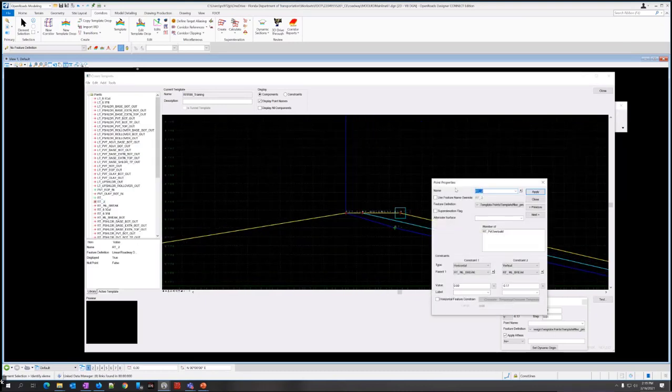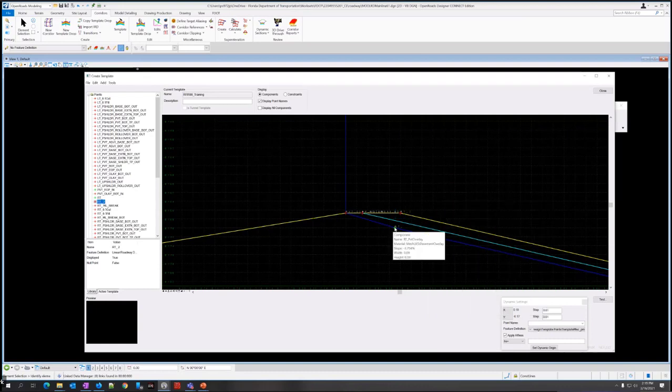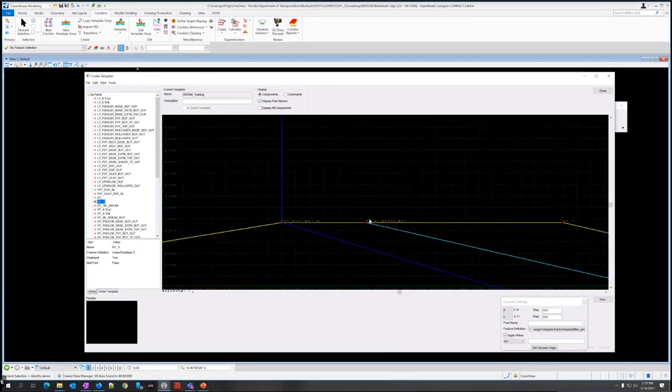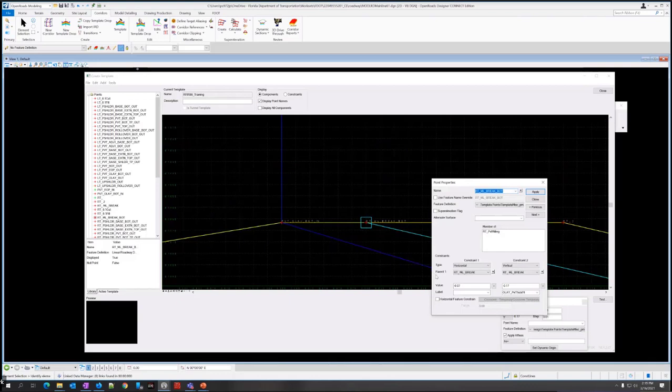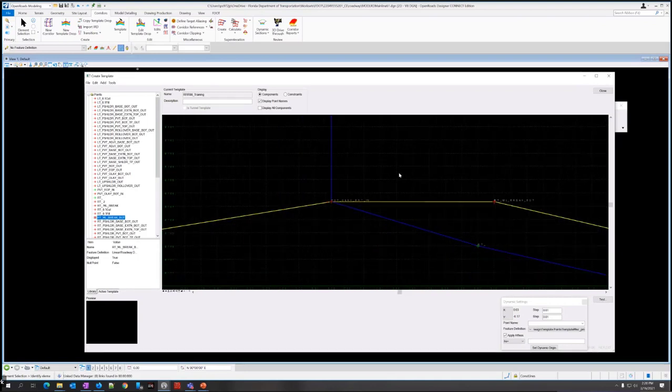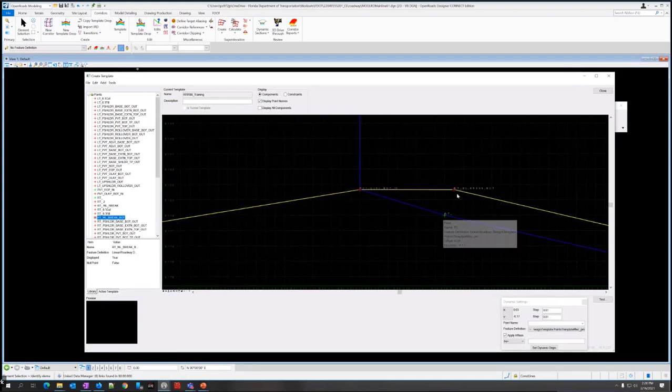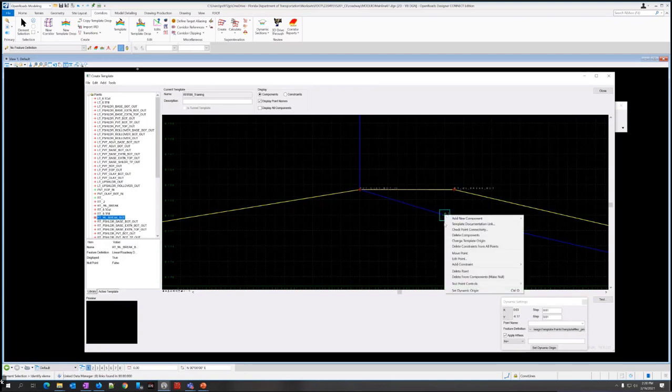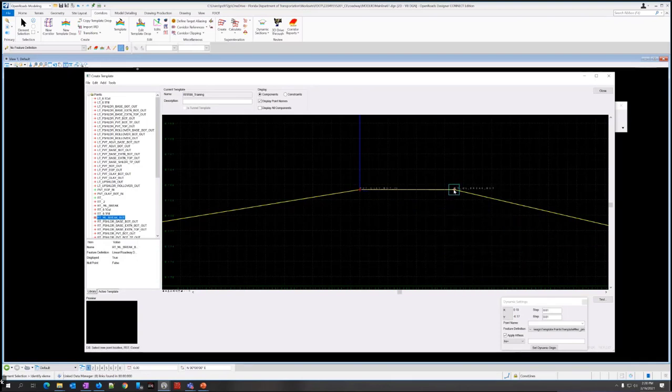That's weird. I'm going to edit it because that doesn't look quite right. Yeah, it does. And actually the name doesn't matter for this because we're going to merge them into one. But let me just check my constraints. Okay, that's what happened. This horizontal constraint was supposed to be 0. So it should be right on top of each other. There we go. Now these 2 points are right on top of each other. Since we're just trying to merge this, this is not constrained. I'm just going to do a move point over here. And if I snap to there, it turns white.